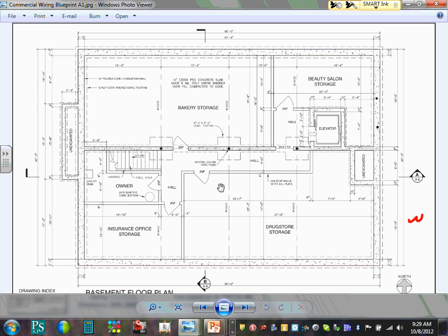Architectural, guys, will give you the dimension, the thickness of the walls, the doors, the windows. Why is it important? Because when you do estimating and you want to cut right through a wall or ceiling, it's very important to know what type of wall. Is it a concrete cast wall? Is it a sheetrock wall? So it's very, very important to get this information.